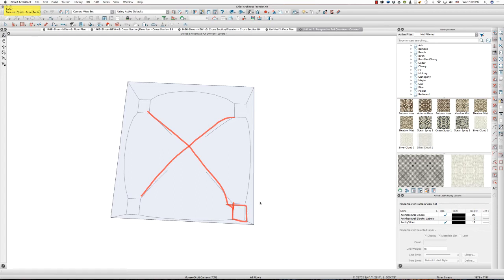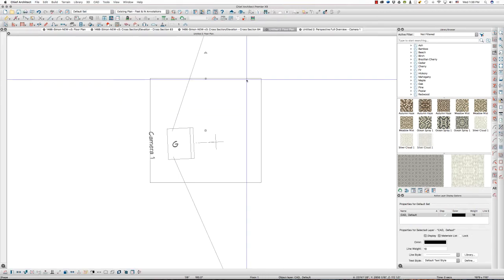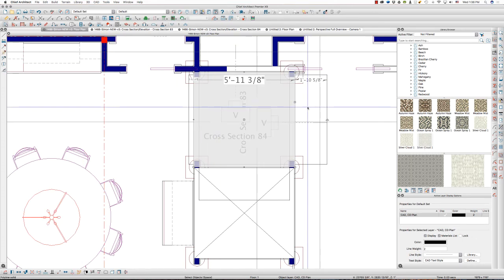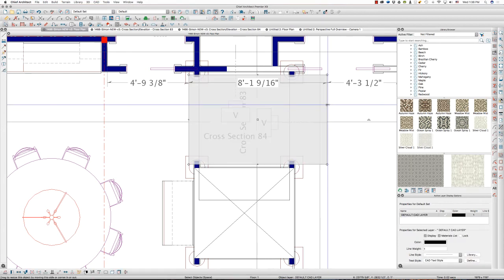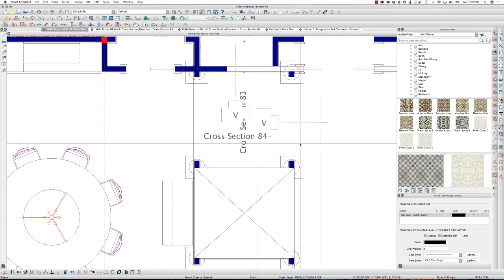Now guess what? The beautiful thing is, because I used Command Option V, my paste hold in place, I can actually grab this solid, this shape, and Command C. Copy this, go back to my floor plan here, and I'm going to delete all of these items. The rectangular box and the two cylinders. And I'm going to Command Option V to paste hold in place right back where it came from.